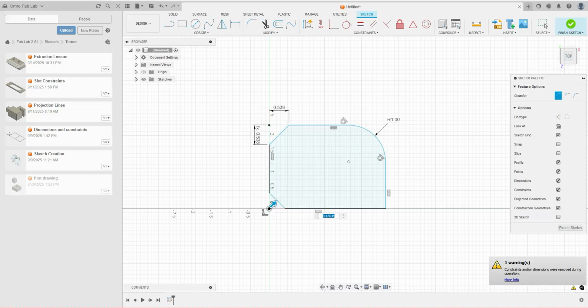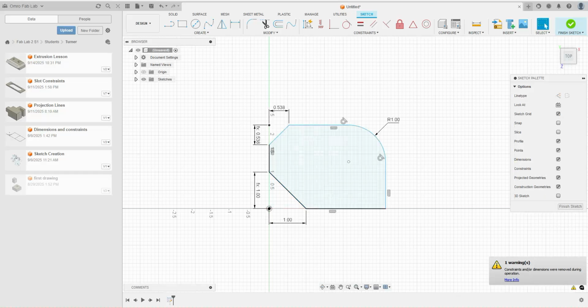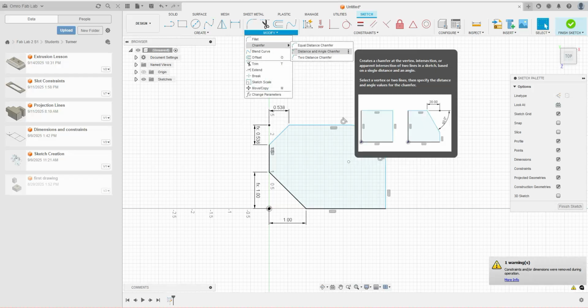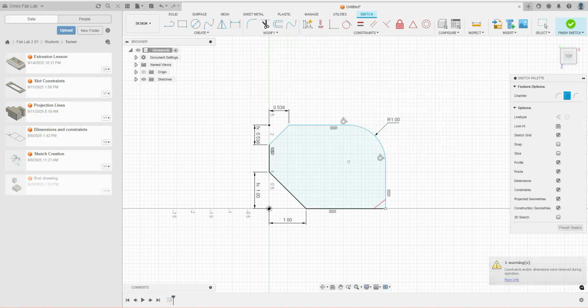The chamfer, you can click on a couple different types of them. Okay, some can be equal from one edge to the other based on the point. Okay, and some of them will have an angle involved. Okay, so you pick a distance back and then you can tip the angle. And then notice here, if I go too far and I intersect with that rounded edge, it kind of deletes it. Okay, so you can't overlap these.